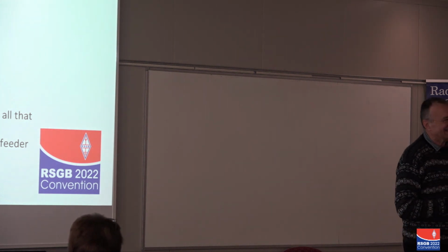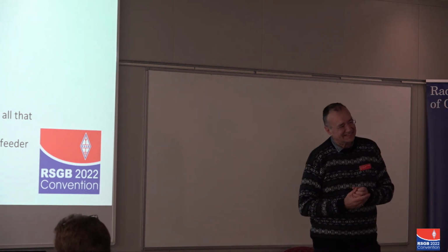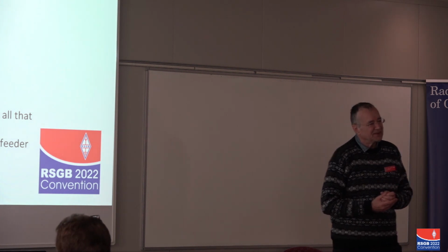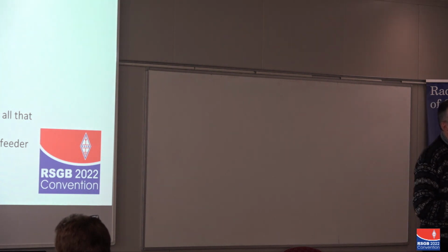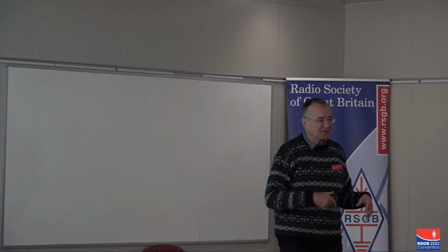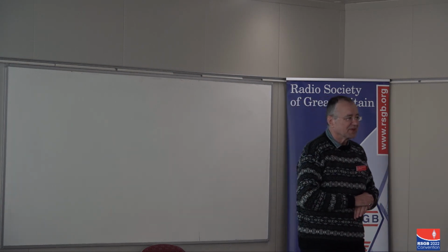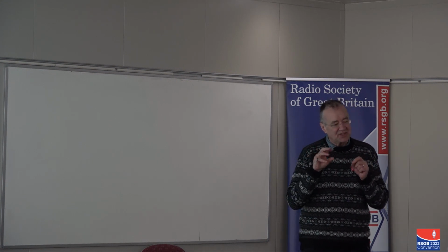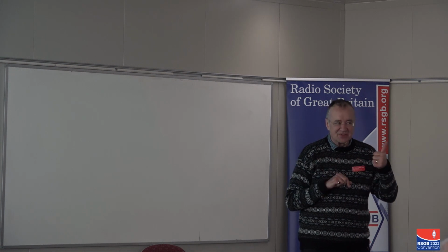I'm not sure you're correct in saying that your receiver has a 50 ohm input impedance. It doesn't matter really what the receiver input impedance is. If it has been manufactured in order to work best with a 50 ohm impedance, then it might have an input impedance of 5 megaohms or something. But if it works best with 50 ohms and you have tuned your ATU to give you 50 ohms, then it's all right.